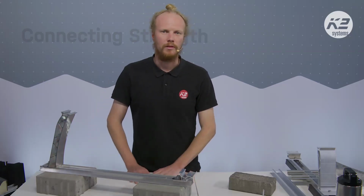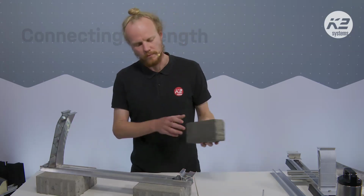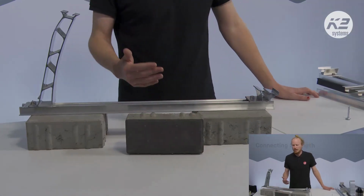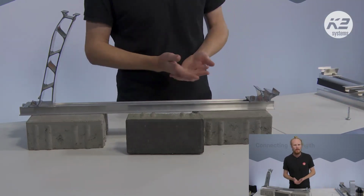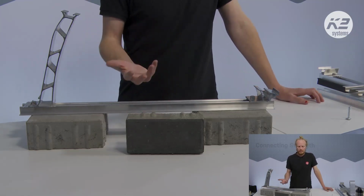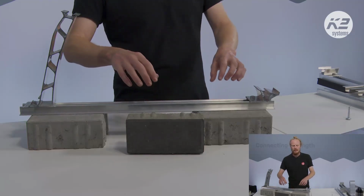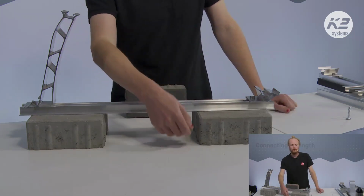If you have a membrane roof, you might have an issue with the contact layer and need some form of protection mat or a second layer of the membrane before you put the ballast down on top of that. But the ideal situation is for green roofs and also gravel roofs, where you can nestle the concrete into the ballast.